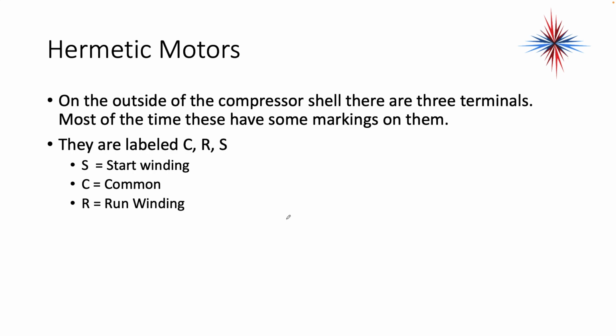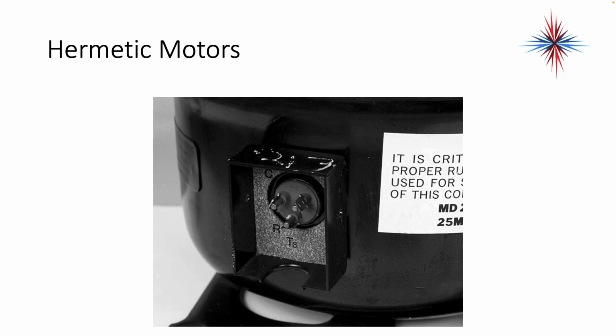Most of them are labeled someplace C, S, and R. Sometimes, over years, that labeling will wear off. Okay, this is a picture. You have a hermetic seal there. You have your common, your run, and the third has to be a start.